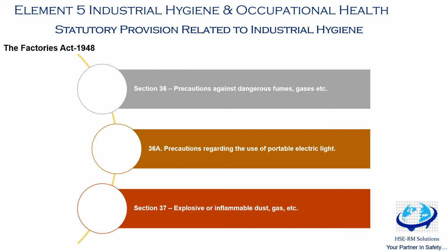Part B is, such person has to wear suitable breathing apparatus and a belt securely attached to a rope, the free end of which is held by a person outside the confined space.